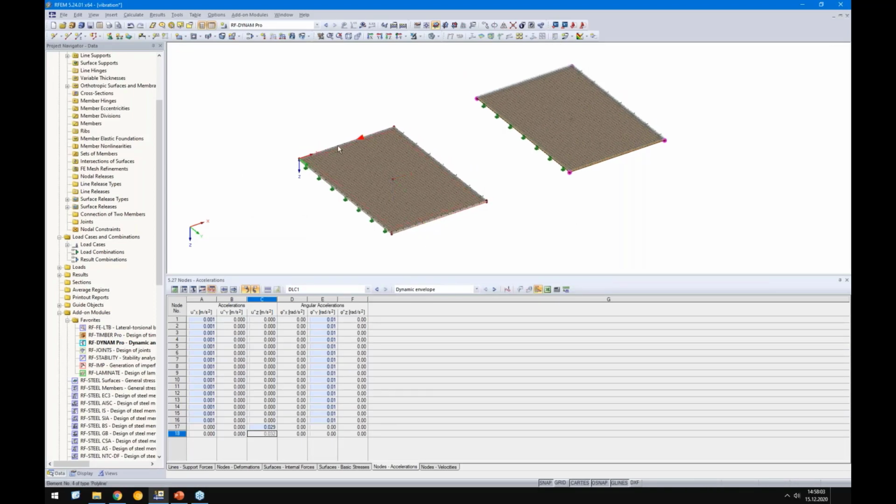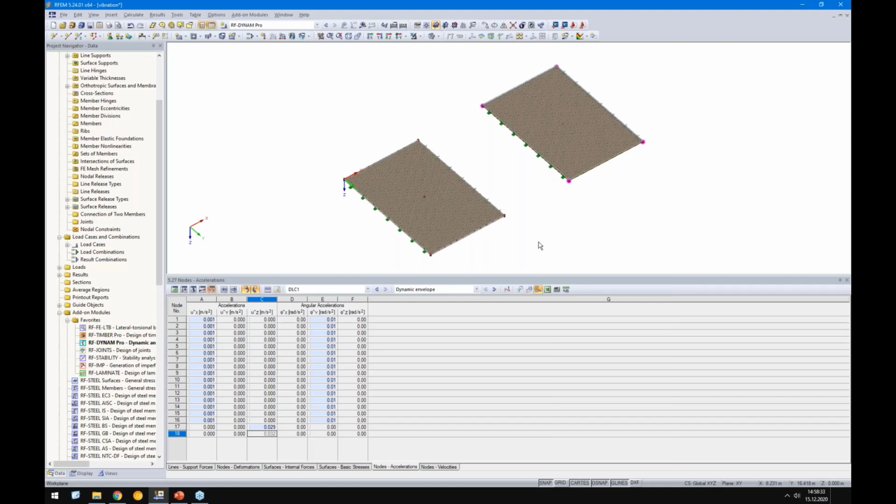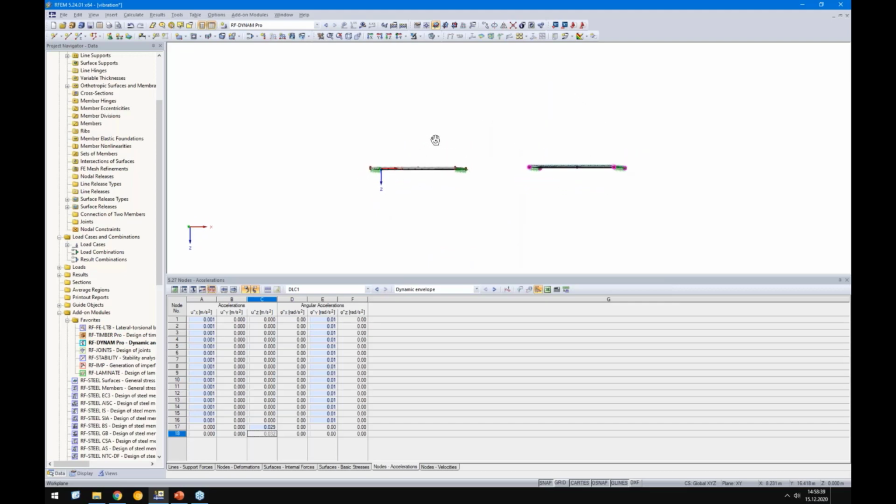And of course, you can add the supports here and here. So support it on 4 sides and run the analysis, copy the angular frequency again, insert it in the time course monitor, and then you will get exactly this 0.065 meters per square seconds. But this is your homework, and for me, that's all from today. I hope everything was clear with this approach and with the defining of the contact solids and the surface releases. It's a mighty feature.